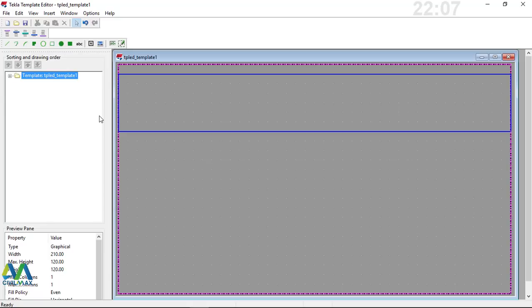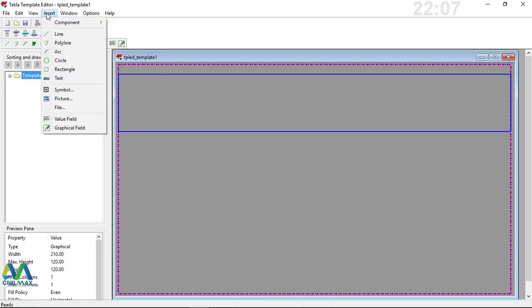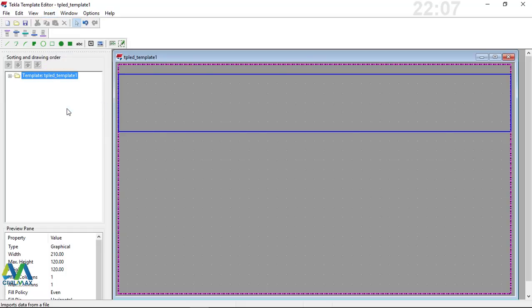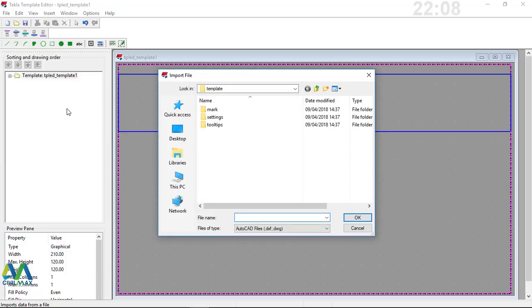After this step, we'll go straight and now pull that file of AutoCAD title block from where it is. Now to pull it, we'll go to Insert, click on Insert, then scroll down to File, click on File right there. After clicking on File, we'll be given the routes where we might get our file. Now I placed my file on desktop, so I'll click on desktop here.